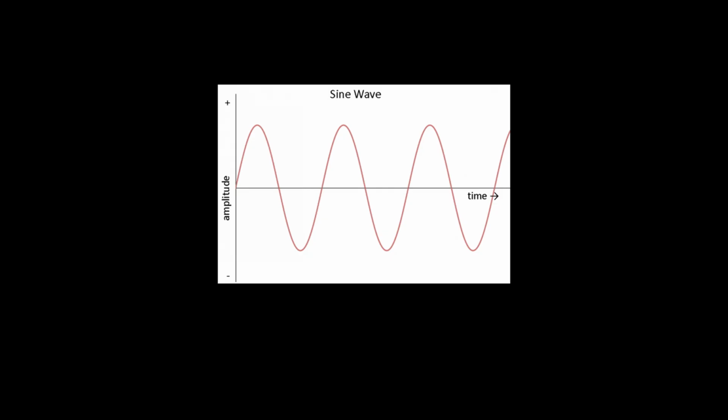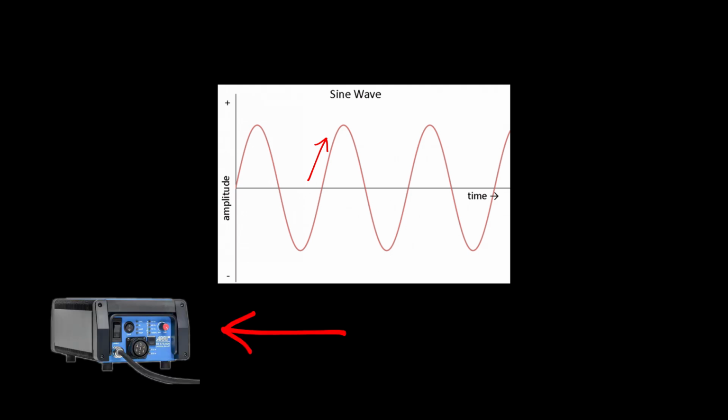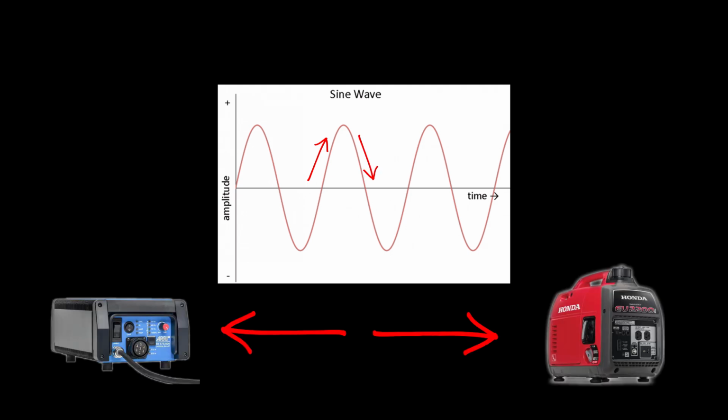These have ballasts, motors, or coils, and you're going to be damaging expensive components if you run them on low voltage. Any light that has a coil, motor, or ballast is going to create resistance and inductance. This is going to get complicated for a second, but I'm going to try to put it in layman's terms. As the current increases and decreases over 120 times a second, like the sine wave for an HMI light, it creates resistance in the current. As the current increases, the circuit stores energy in a magnetic field or ballast. Then as the current decreases, the circuit gets the energy back.